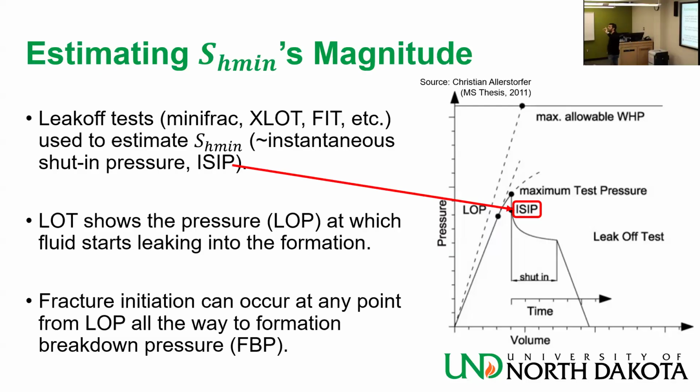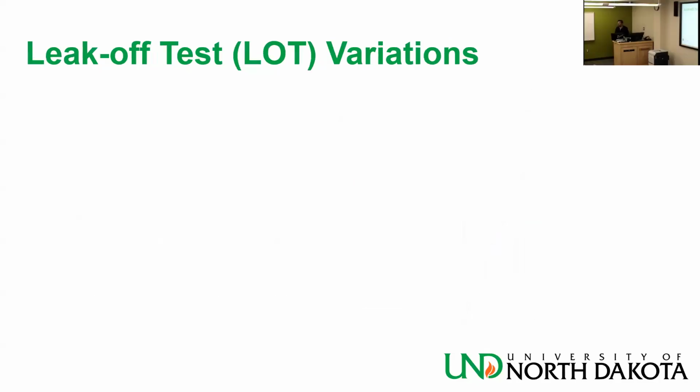Okay, any of those tests, mini-frac, extended leak-off test, and so on, they all try to get you close to the point where you generate what we call a tensile fracture. And we're going to talk about those later on. Tensile crack. Any questions? So this is how we measure the SH min, or we constrain its magnitude. But there are lots of ways you can skin the cat. All of them are effective. There are several ways you can run this leak-off test.